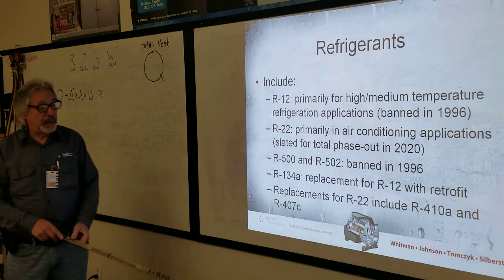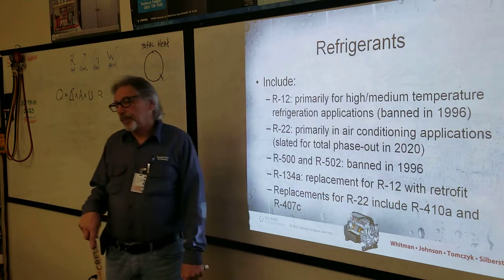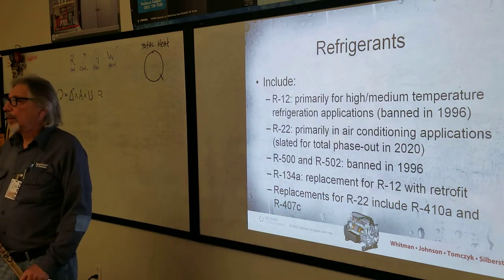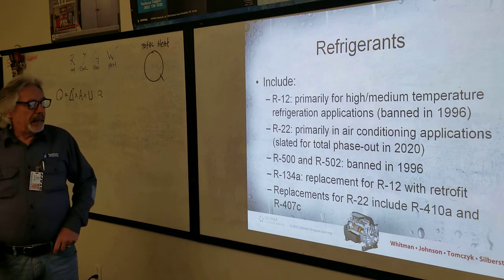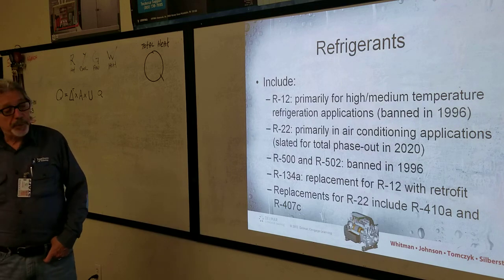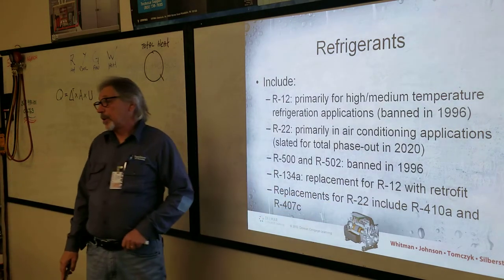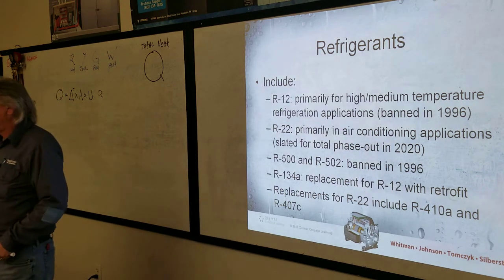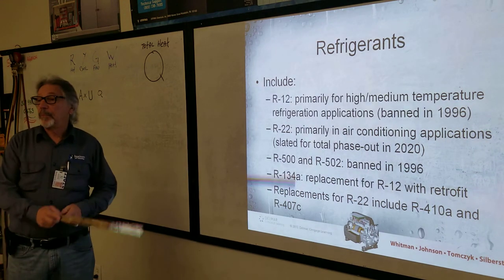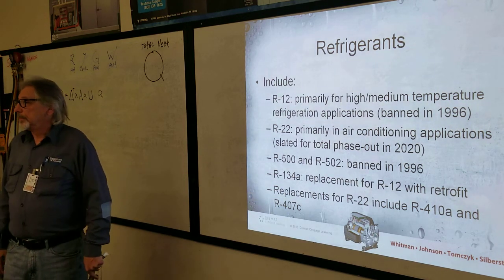It's a special refrigerant created by Carrier, and they built their systems to handle the pressure. This is a higher pressure refrigerant, so we're going to have higher pressures. You can't just put a high pressure refrigerant in a medium pressure system like R22. It'll blow it up.